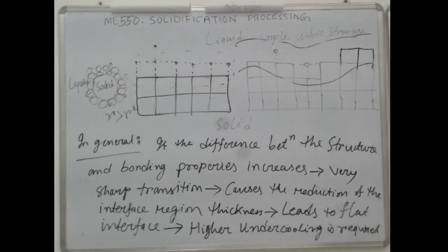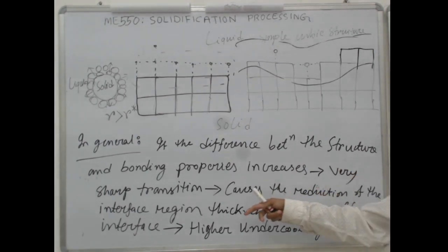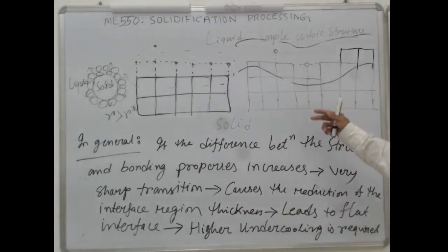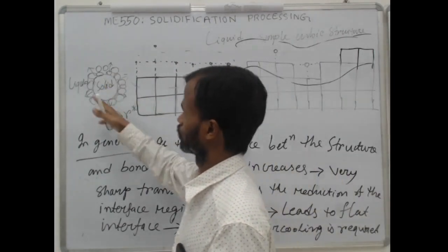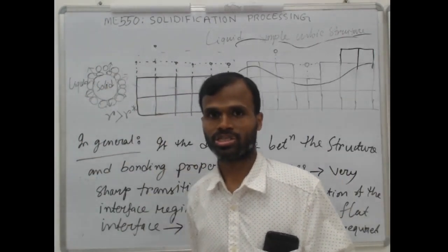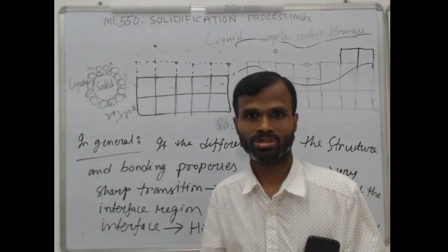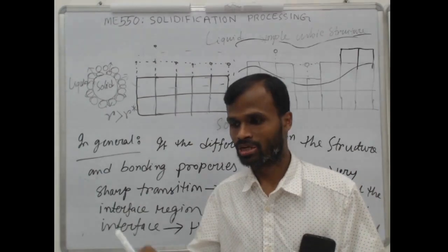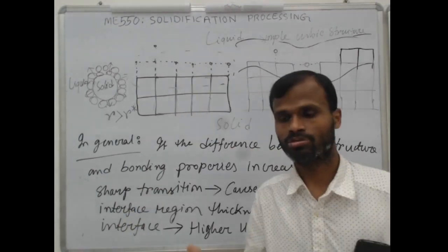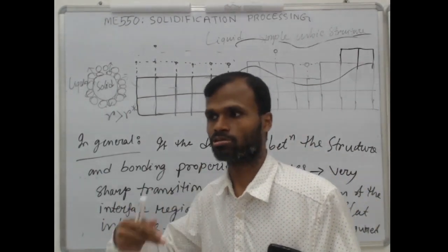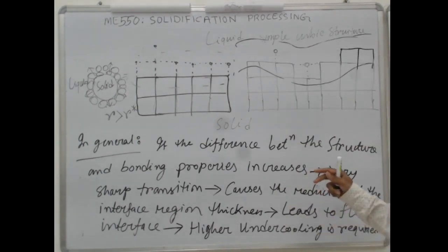So in that case the solidification becomes easier, and you get isotropic growth. That means growth is almost uniform in all directions, but local anisotropy, because of solute and the interface energy, actually gives us dendrites. That we will be discussing later, but try to remember these things.